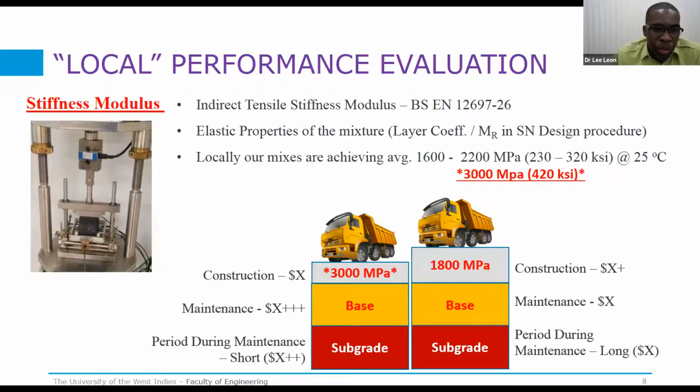So we can see that the pavement structure will be thinner, but it will not be able to withstand the loading. So we have more maintenance to do on the adopted design as compared to less maintenance and a wider gap between the periodic maintenance. So in terms of the life of the pavement, the maintenance costs will increase, and the number of maintenance procedures, or even the methodology, what type of maintenance to do, will increase if we have the adopted design with the wrong values or the wrong inputs of the actual materials we have looked at.